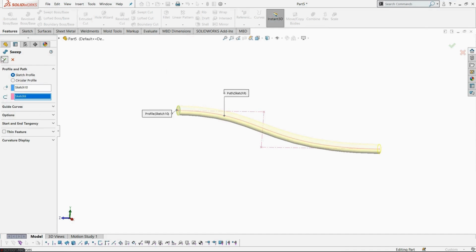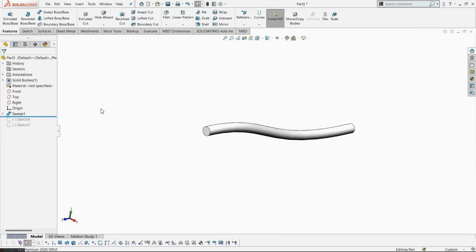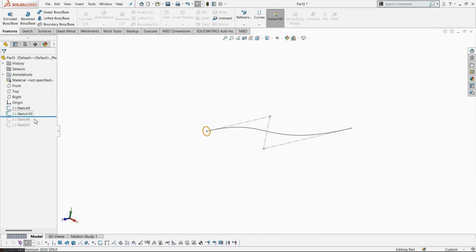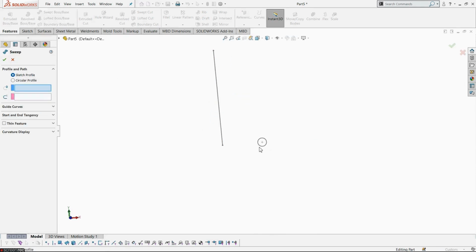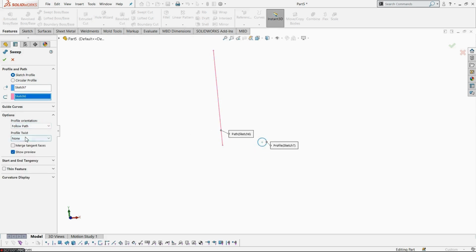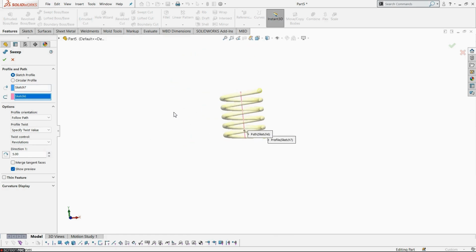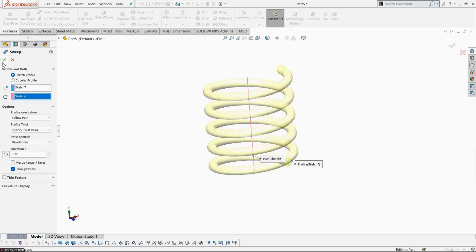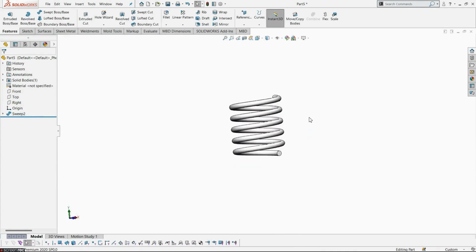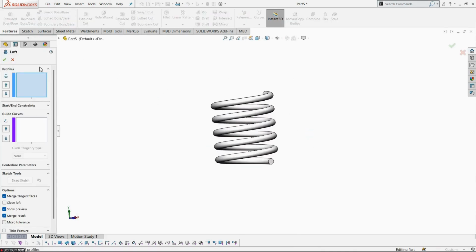Also, if you look at the swept boss options, we use the profile and path curve to make pipe-like designs. Within these swept boss features, with swept sketch profiles, we can make a spring-like formation, instead of using a helix profile and helix curve. We just want to know what the different options are and what the exact use of each is, with each and every part and an example. Okay, that is the thing. Why an example? Because only then can you clearly know what the exact tool is.